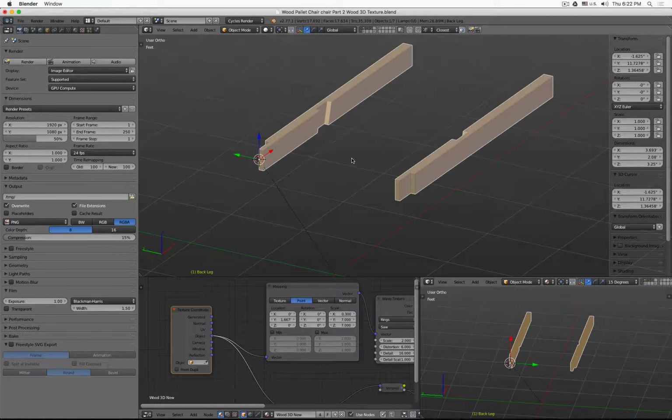There's actually one other way how we can define or manipulate the position, rotation, or scale of a three-dimensional wood texture. The advantage of the current method, which I showed you, by in edit mode rotating the mesh correctly so that in object mode we can position the piece of wood as needed, is we have to one time set in edit mode the mesh growth direction correctly, and then we are free in object mode simply to rotate the object, and the texture always rotates correctly.